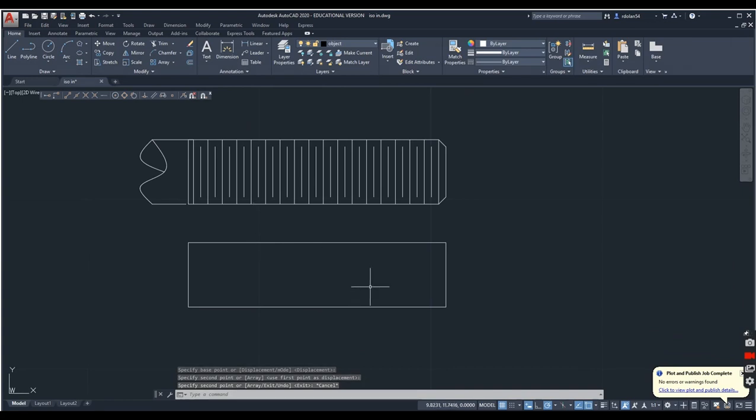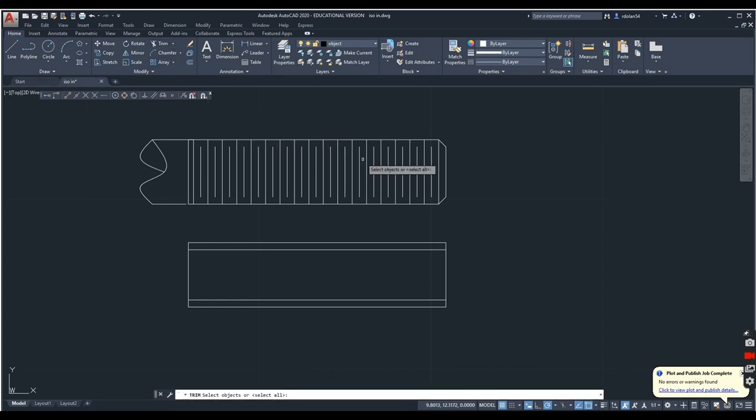Okay, now we're going to make our simplified, and I will offset 0.021 again from here to here and here to here. I will make a chamfer. Distance is going to be 0.21 in both ways. I'm going to chamfer here and here, here and here.